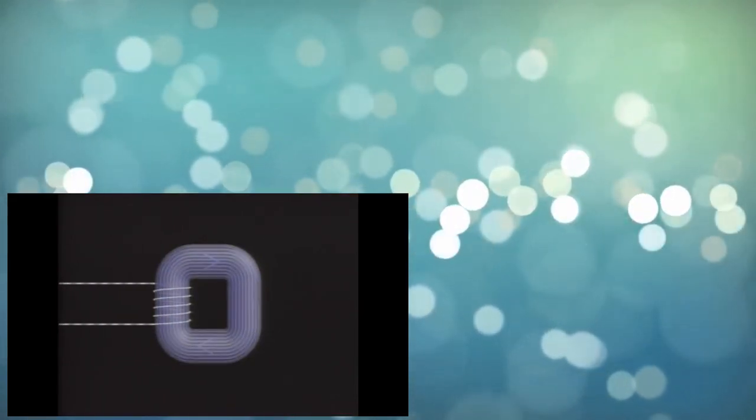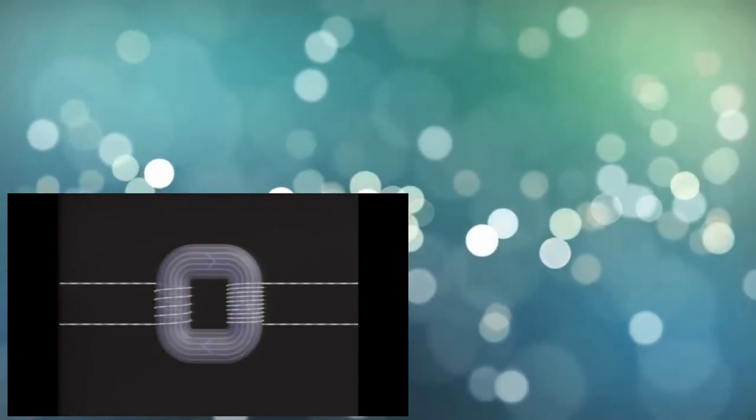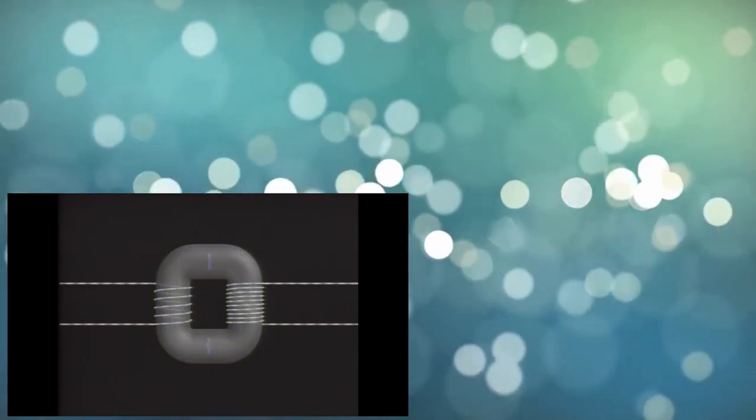And if a secondary circuit is wound around the ring, as the changing flux passes through it, a voltage is induced in it. That voltage is proportional to the number of turns around the iron. Obviously then, the voltage of the power transmitted to the secondary circuit can be made higher or lower than the voltage in the primary circuit.